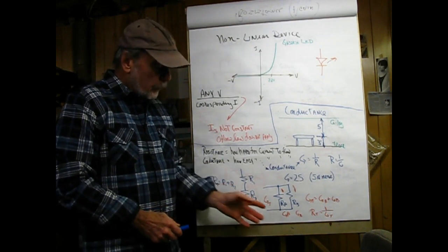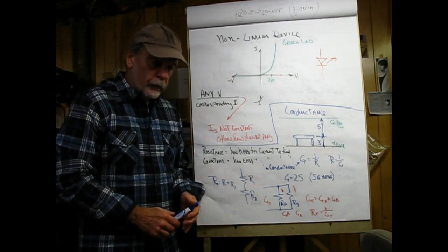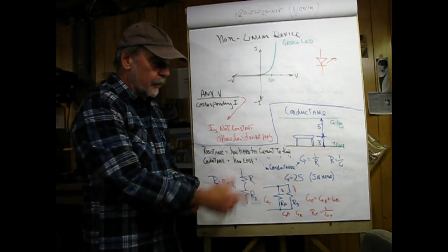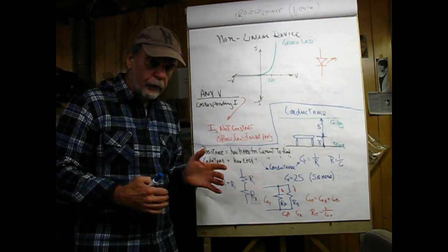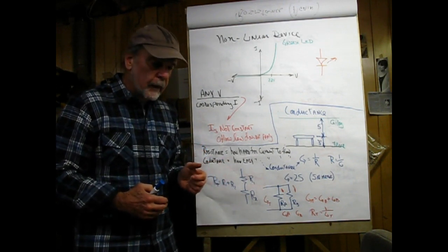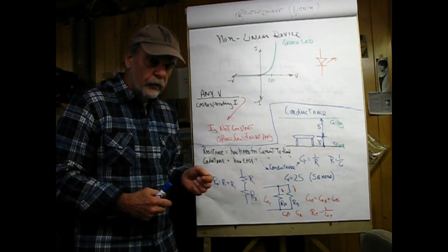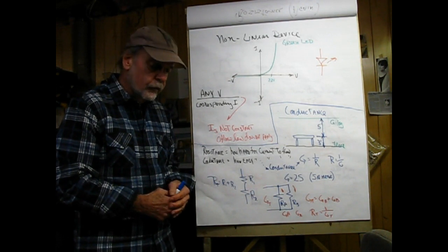What I was saying is that if we had, say, 4 resistors in parallel, and we'd be solving those using the R subscripts for resistors, probably not using the conductance at all, but what sits inside of that formula, which we'll be learning about later, is inherent conversions into conductance. Then we do the adding, and then we convert it back into resistance.